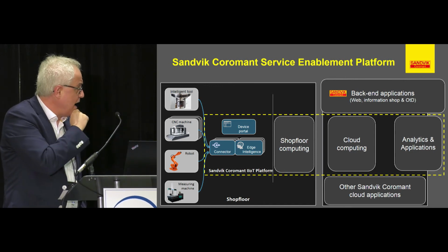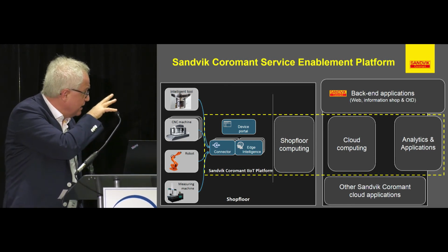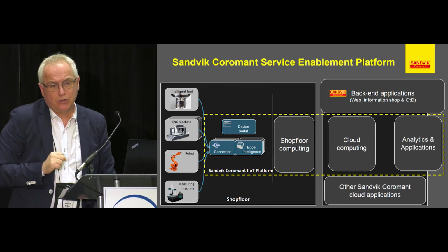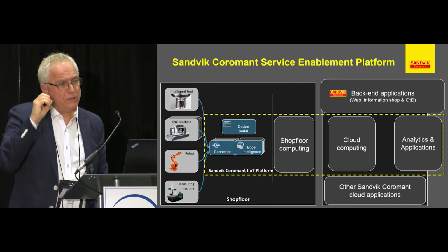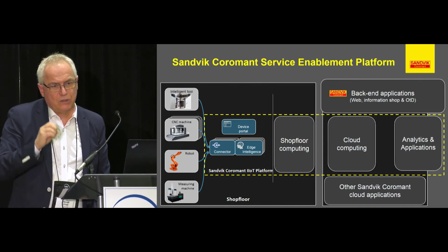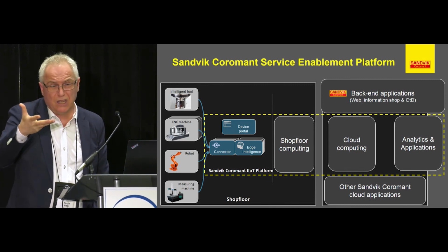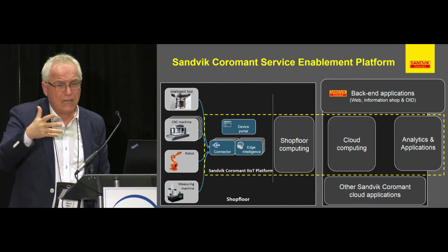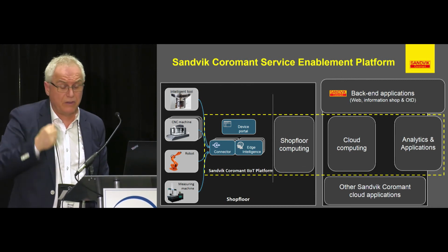With this connectivity supporting 5 milliseconds, the edge intelligence side is a distributed architecture. If something happens with the machine, we can't wait to respond back to the cloud, because sending that information up to the cloud and back to the machine takes almost 10 times more. The 5 or 6 milliseconds becomes 60 or 65 milliseconds.